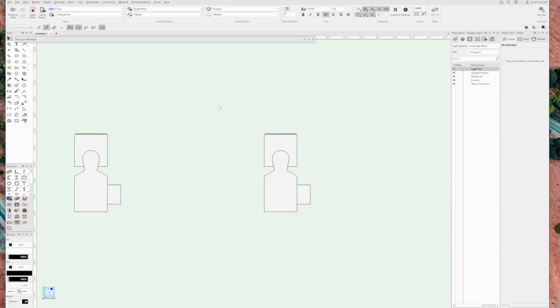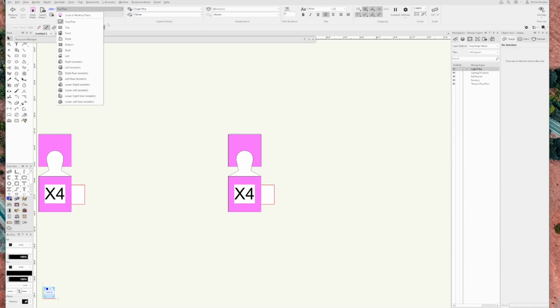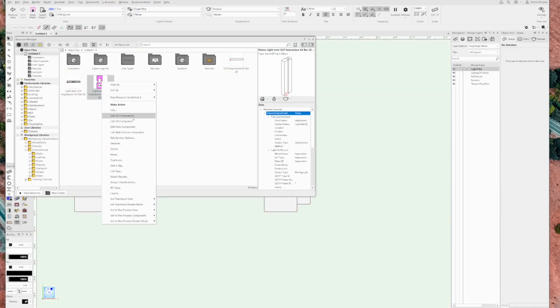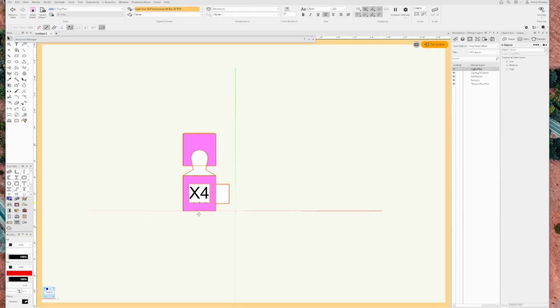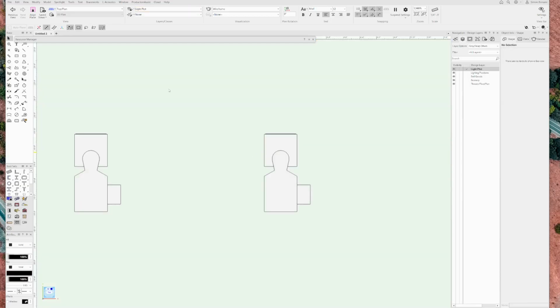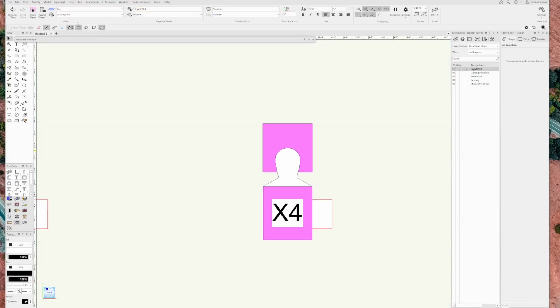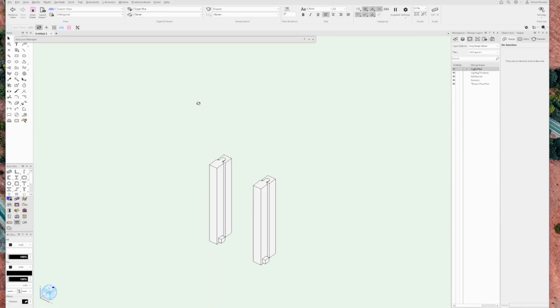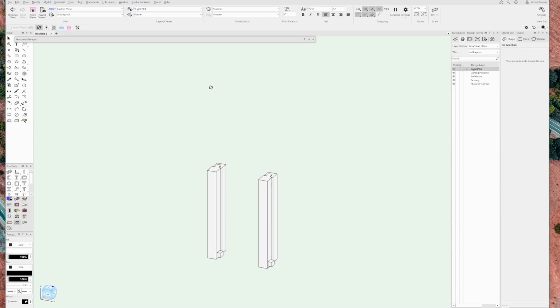So that's why when we create the 2D and 3D, we really align them carefully and we flip from top plan to top to make sure that it's perfectly aligned before saving and actually making a plan with it. If I go back, the center of the base, go back to 0, exit, let's flip the top to top plan, and then back, and that's perfect. And that's how you create custom 2D geometry for vertically installed lighting devices.